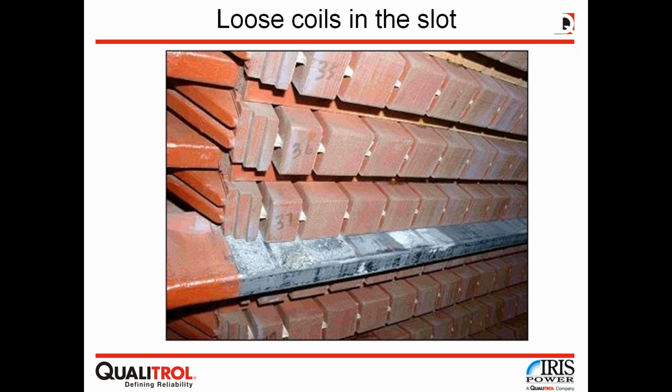The number of pulses per second is an indicator of how many voids or gaps you have, and the amplitude of the pulses is an indication of how big that gap is. However, there is no clear correlation saying that a 500 millivolt pulse corresponds to a 1 millimeter gap. So there is no such rule.